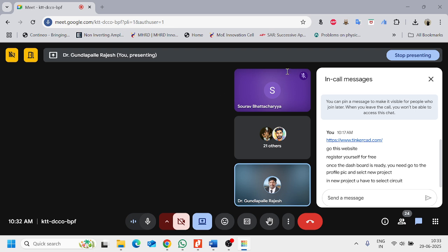Then in the setup we are going to have the pinMode. Now see this pinMode function. pinMode is a function which will configure the pins, whether it is input or output. This OUTPUT is case sensitive. You have to be very clear with this. You can't write a small letter like this. It should be capital letters, OUTPUT. Now pinMode is an output mode.